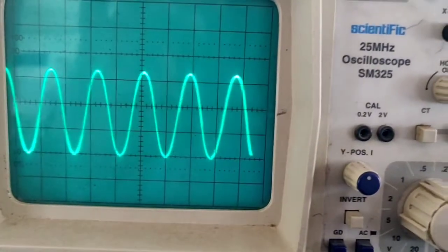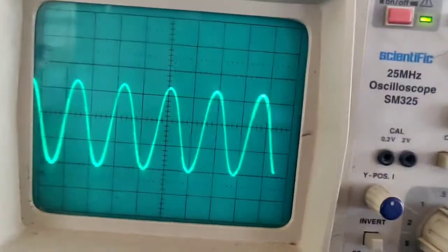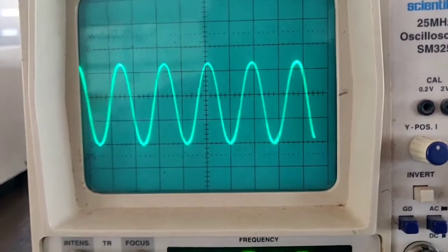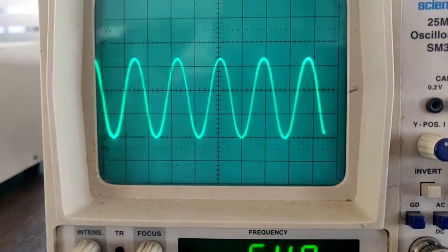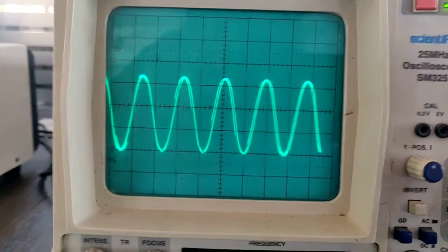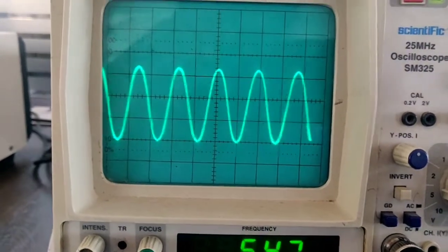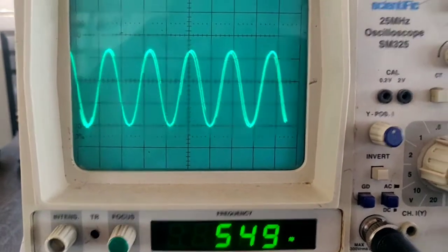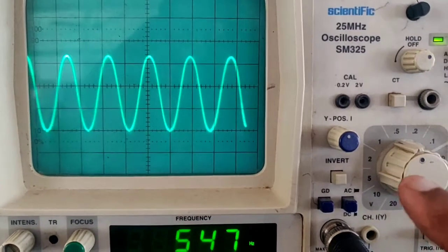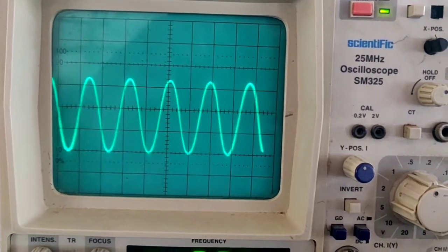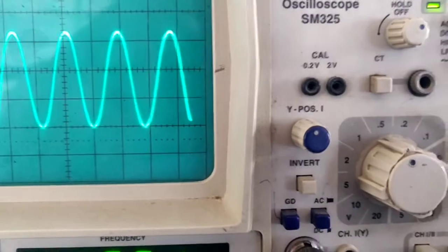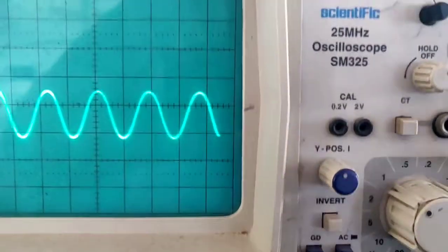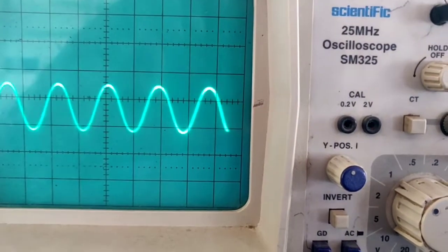So multiply these two, you will get the amplitude here. Suppose you want one particular experiment, 1 volt peak to peak, what you have to do? Assume that it is 1 volt peak to peak you require, any value. See, the best method is to select the scale first. For example, if it is 1 volt peak to peak, which volts per division scale do I have to select in the beginning itself? The best way is 1 volt scale input voltage, meaning if you want to set 1 volt peak, select 1 volt scale here. That is correct.